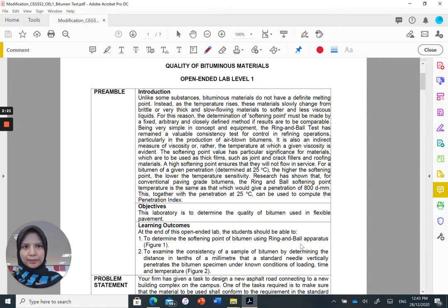If you were doing it in the laboratory, the assistant engineer would prepare this bitumen, right, in a hot condition, right? Make sure when you are doing this penetration test, the state of the bitumen must still be hot, right? Okay. If it is already cold, it would be hardened, right? So you need to have just a nice temperature for you to conduct the experiment.